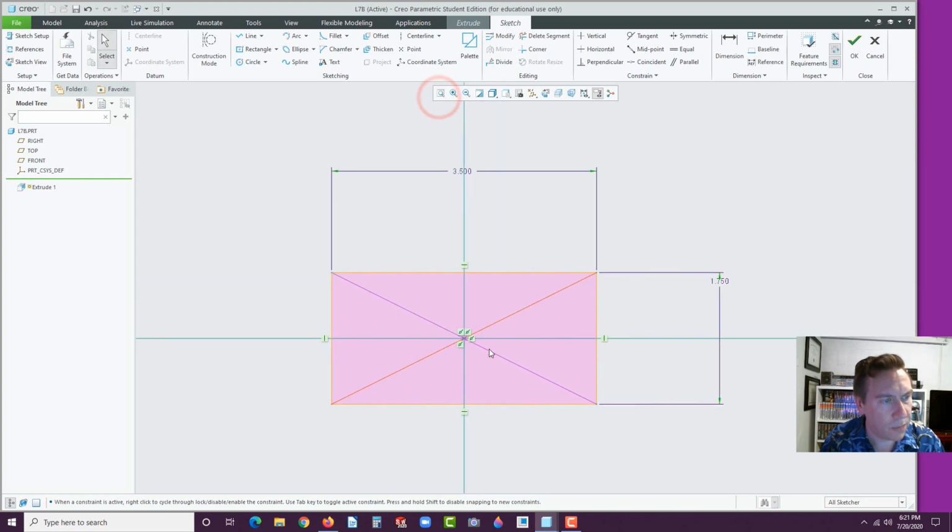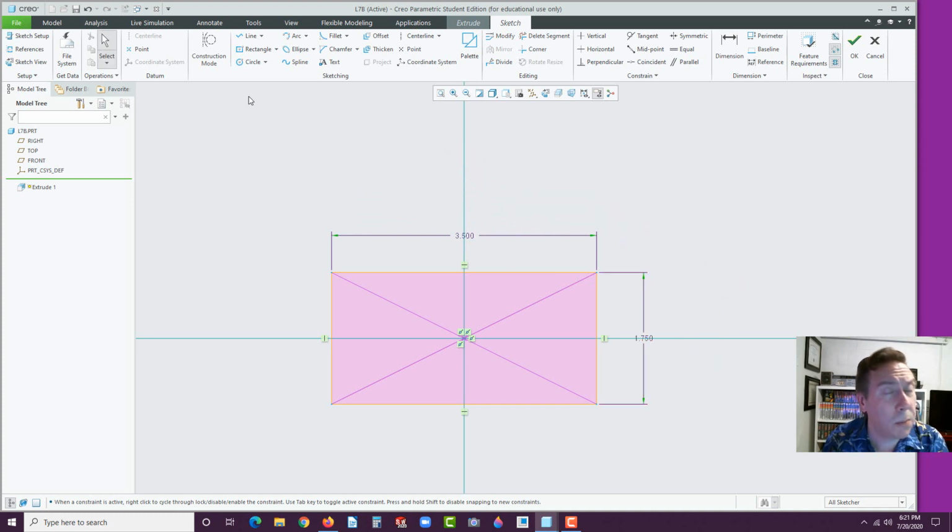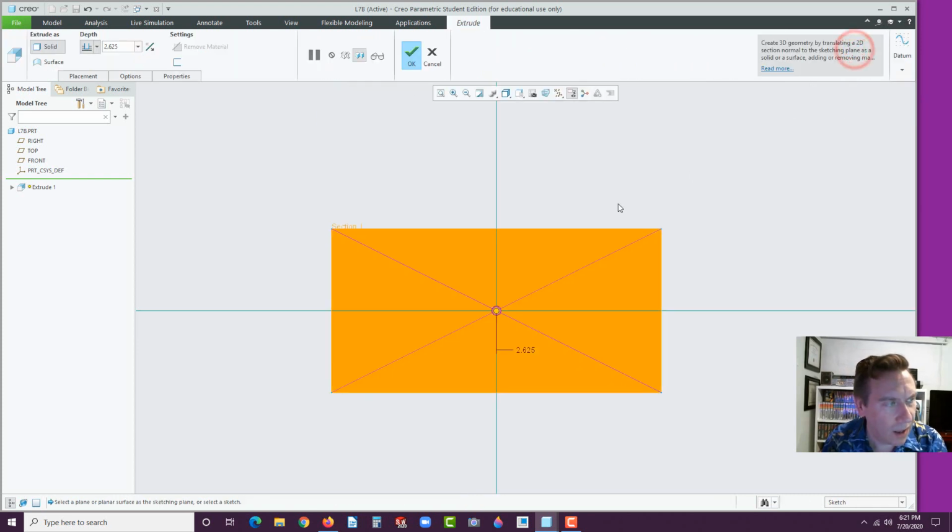And refit it. Okay, looking good here. Let's get those chamfers on. We could put them as a regular chamfer, or we can make sketch chamfers. So if you want, you know what, I'll just use a chamfer tool as a solid. That's fine. We'll do that later. Let's go and hit OK.